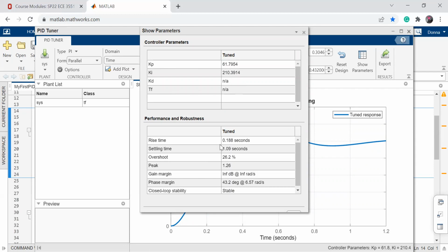Yes, that's the cool part. That is the step info information. So if you wanted your rise time to be less than 2 seconds and your overshoot, wow, that's 26, a lot. Let's say your design requirement is rise time less than 2 seconds. So if you were to put the KP and KI, yes, it will be the same in the step response. So this is kind of the trial and error for you.